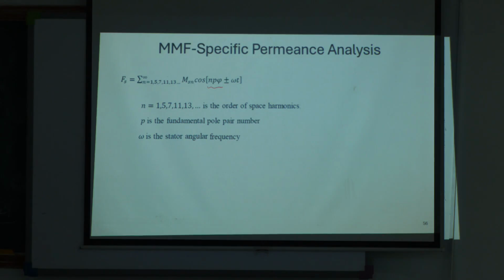Okay. And what is phi? If you recollect the 2 circles that I have been drawing since morning, phi is the angular frame of reference on the stator side. So phi is the stator reference frame, an angular measure in the stator reference frame. I will also introduce an expression where phi dash is the angular measure in the rotor reference frame, and omega r is the frequency associated with rotational motion on the rotor side.